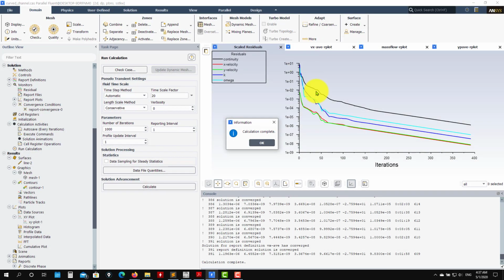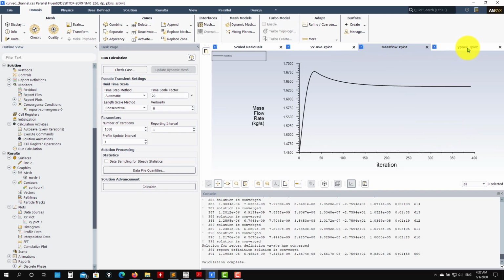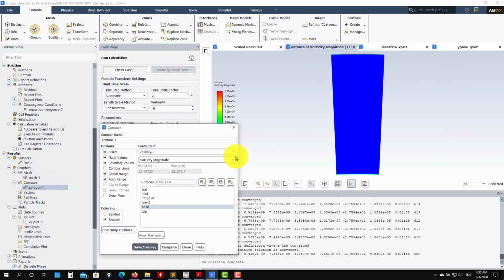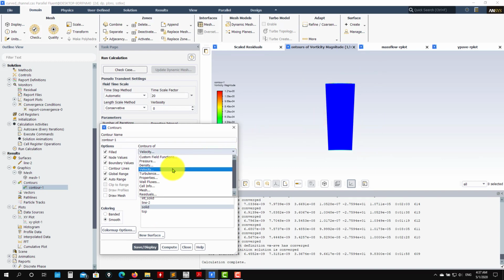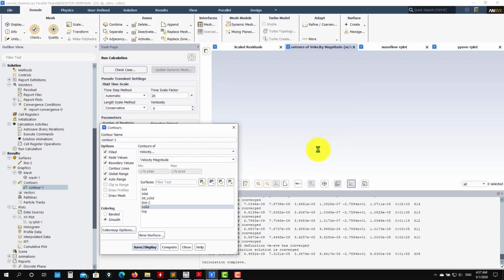Okay, I'm back. So here in almost 400 iterations, we have resolution. See that the residuals are falling in a monotonic way. Very nice. It still maybe would be a good idea to let it run a little bit, but let's take it for granted that this is an okay solution. So what we need to do, well, you can check your colors as you want. Okay, it's useful. So let's check velocity. Okay, that was okay, and you have everything.